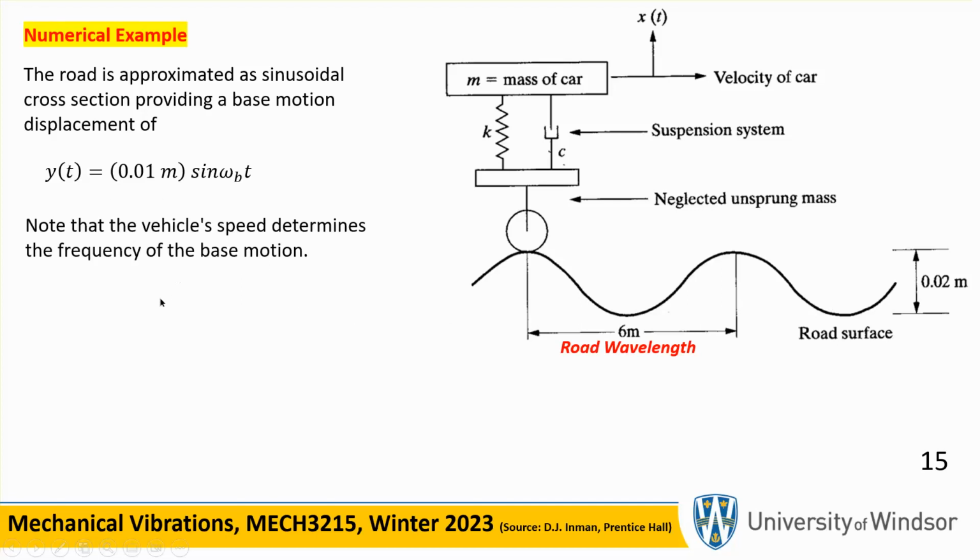All right. Now, first of all, we want to model this. For example, in a particular problem, the road is going up and down by that much. How much does the occupant go up and down? In other words, big X. We want to find big X in terms of big Y, and big Y, by the way, is half of this, 0.01 right there. And then we want to know how much force is transmitted.